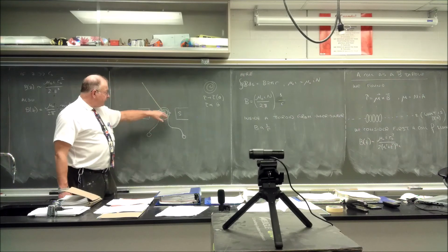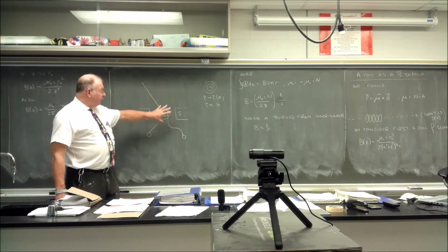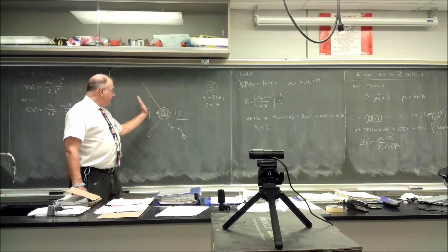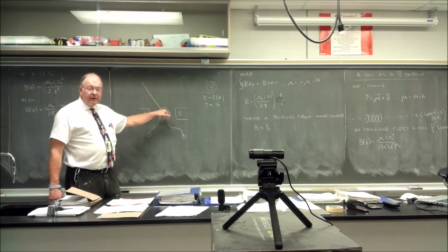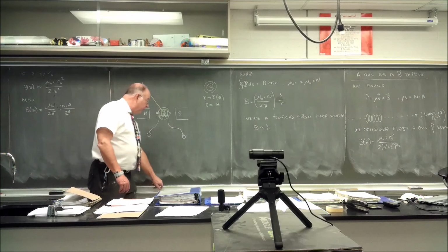The torque of this rotation here is a function of the current. For a steady current, it's going to be some value. So this thing will rotate around until the torque of the spring balances with the electromagnetic torque, and then the wand points at the location of the scale you want it to.